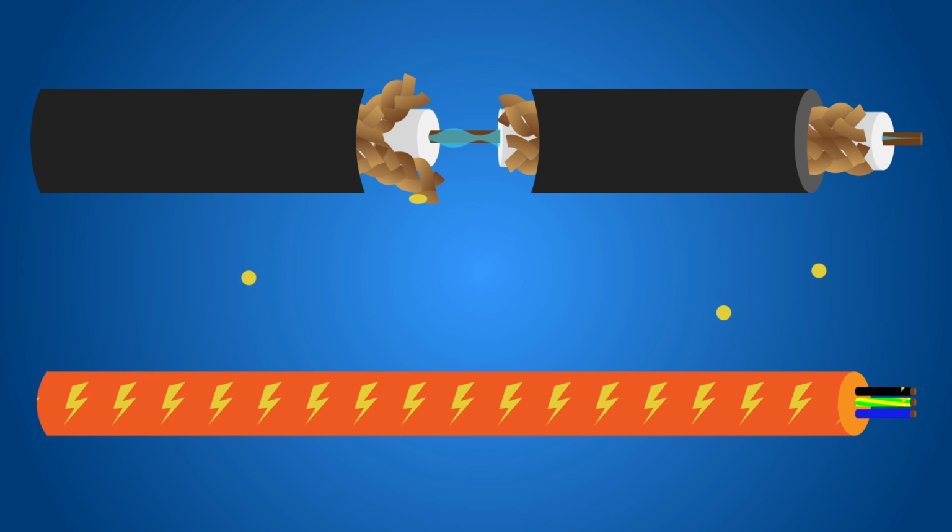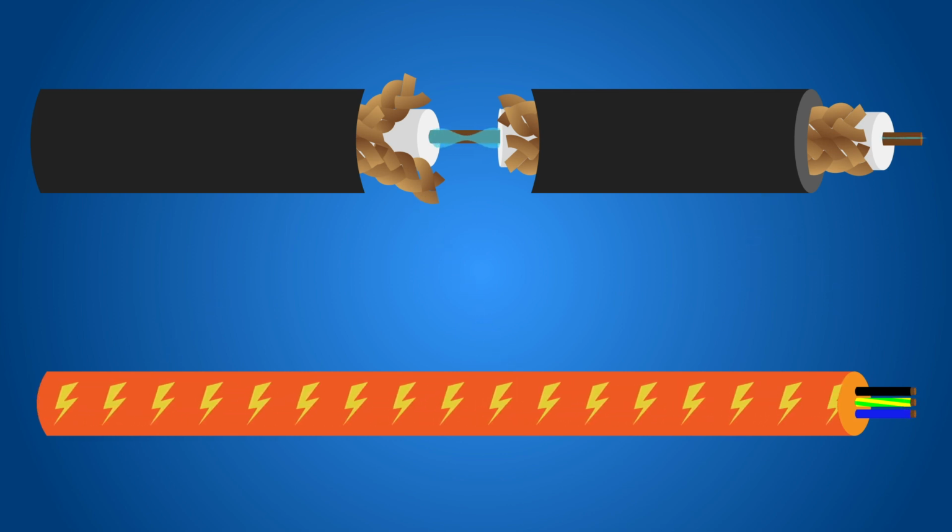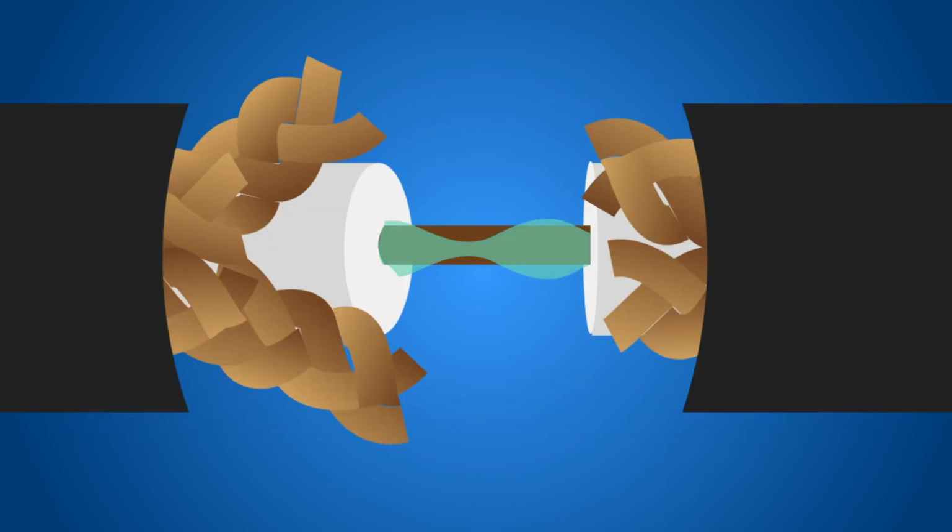This cable wasn't properly shielded, so the electrical signals from the power cable were interfering with the video signals from the RG59 cable. And again, like we said, this was over-exaggerated on purpose. Nobody would ever install a security camera like this. But the point here is, when you're laying your cables, you have to be careful where you're laying them.